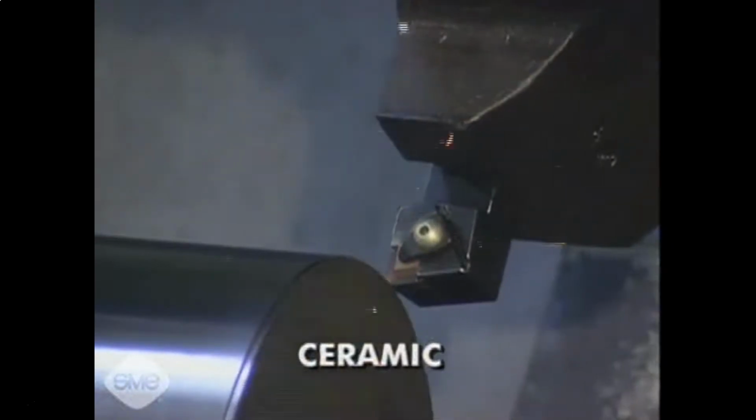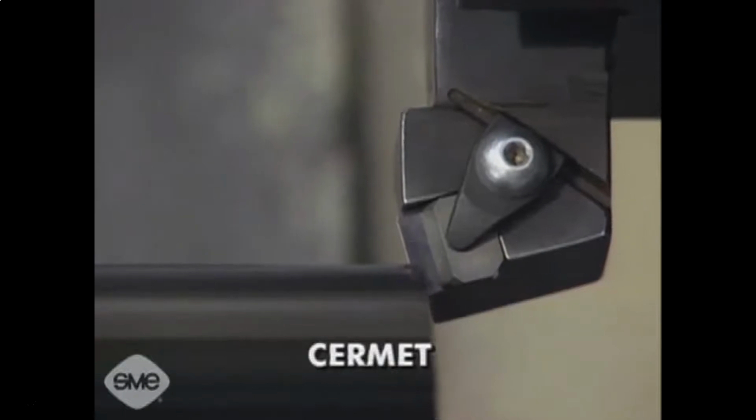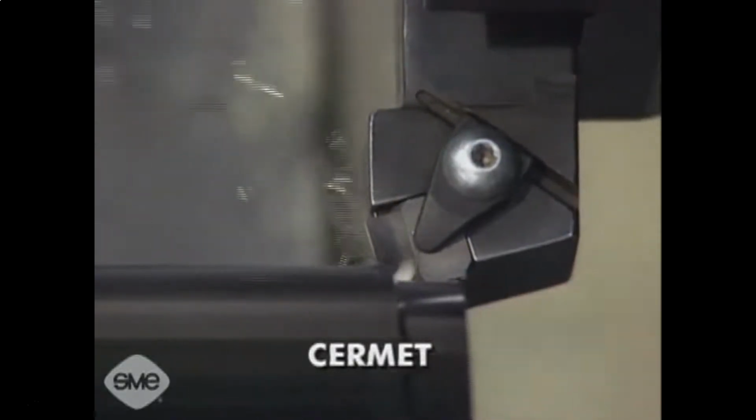Ceramic inserts may be alumina-based or silicon nitride-based. They withstand higher heat than carbide, have good resistance to abrasion, and they cut very fast. But ceramic inserts are less shock resistant than carbide tools, so their applications are limited. Cermets are composed of titanium carbide or titanium nitride with excellent resistance to various forms of wear.